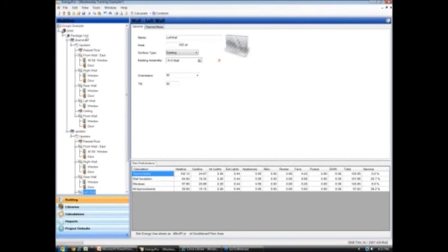So I guess to elaborate on that answer, as a participating contractor, you're going to submit an Energy Pro model twice. The first time is before you do the job, at the planning phase. You're going to submit a model that shows the alternatives as you expect to carry them out, with the savings that you expect to achieve. In the example, we start with 25% leakage, and we expect to get down to 15%, and you're going to show us that model. From that, we're going to calculate the savings that would be expected and the rebate that would correspond to that.